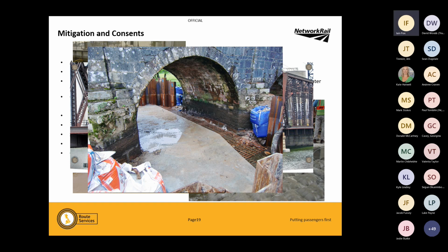We used to get a high risk structure, maybe, for example, Pier 2 might be a high risk, and we would protect the whole asset. Nowadays, we're not allowed to do that. We can only protect what is at risk. Now, the problem with that is if we protect a part of the structure, we then need to look at the rest because we may have moved that risk to another part of the structure. So we need to think about that as we're designing.